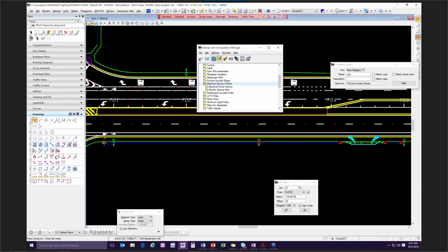So as I come up to this pole box, I have 9 lines at least, and I'm going to have 3 that are going to drop out to go to this pole. When these 3 lines drop out to go to this pole, per line, I need 8 feet added at this pole box. I also need another 8 feet at this light pole.